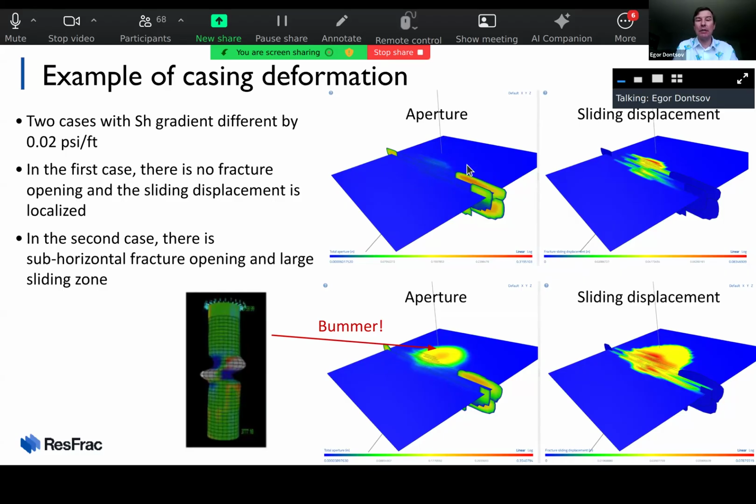Yes, we pressurize it, pressure diffusion goes in, and then it causes failure. But it's very localized. It's all limited by pressure diffusion in the fault. Yes, you can have high hydraulic conductivity of this fault or bedding plane, and now it will go further, but it's very limited. But as soon as you add just a little bit of pressure, now you are able to open it up to have this large scale aperture.